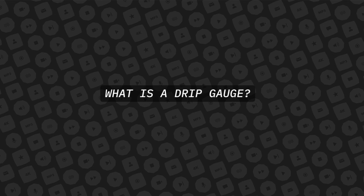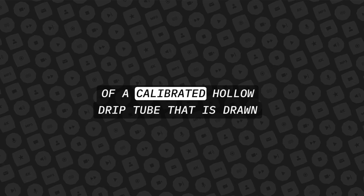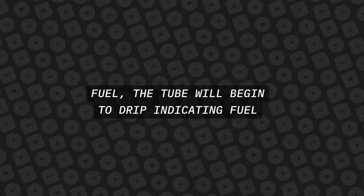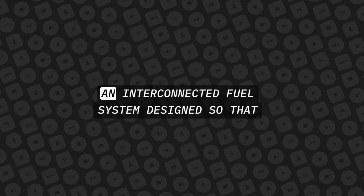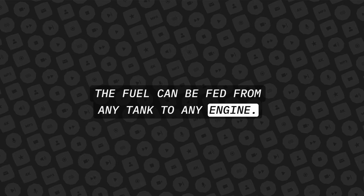What is a drip gauge? An underwing bayonet-type fuel gauge that consists of a calibrated hollow drip tube that is drawn out from the lower wing surface. When the top of the tube reaches the level of the fuel, the tube will begin to drip, indicating fuel level. What is a cross-feed system? An interconnected fuel system designed so that the fuel can be fed from any tank to any engine.